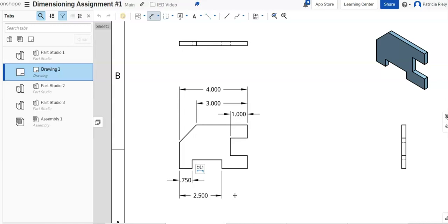What else do I need, do you think? Well, I have a lot of overall. If I thought this was too busy, I could put the overall here, but I'm not going to do that. I definitely need to have this measurement here. If this was width, I need a height and I need a depth. This is a depth from here to here. So let's get that depth in there. It looks a little better if it's like this, because look how hard that is to read. I think that's a better way to present that.